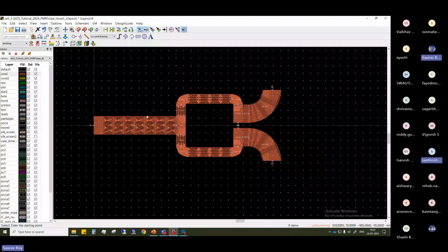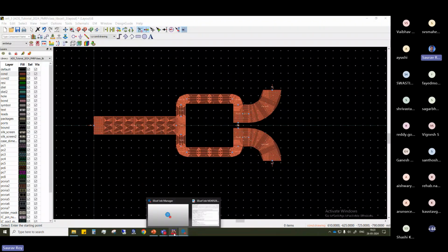Yeah. So now the point is, you see the meshes. You see the fine lines it shows. The electric and magnetic field, current density, all this will be calculated on this mesh. And as you see, on the edges and corners it is very dense because there the calculation is much more required. Very crucial calculations will be there in the edges, because the change will be very sharp at the edges. Otherwise, in the normal lines, you see the mesh density is very low. So now that all this is done, we'll go back once.